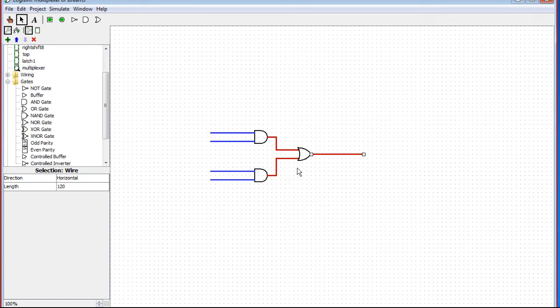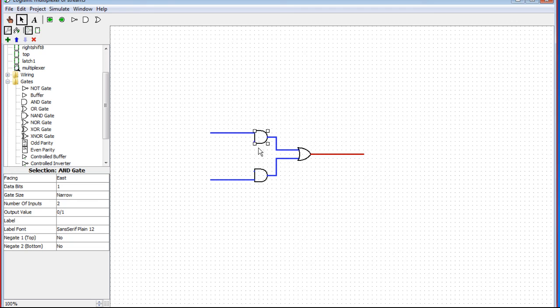Maybe in some situations that kind of stability is useful. I'm not sure. I'm gonna plead ignorance on this case here. And I'm just going to say that personally, I believe tri-state buffers to be more efficient, but in our situation, a multiplexer is going to give us a better circuit diagram, probably better simulation characteristics in terms of performance.